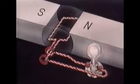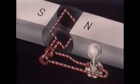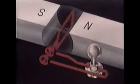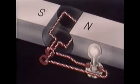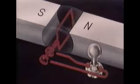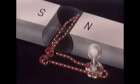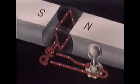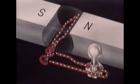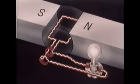Let's examine this rotation more closely to see how a generator works and to understand the nature of alternating current. The particles flowing in the circuit represent electrons, but keep in mind the conventional current flow is opposite in direction. In a simple generator that's connected to an electric light, the greatest current is produced when the conductor passes through the magnetic lines of force at the fastest rate. This occurs when the conductor moves at right angles to the field.